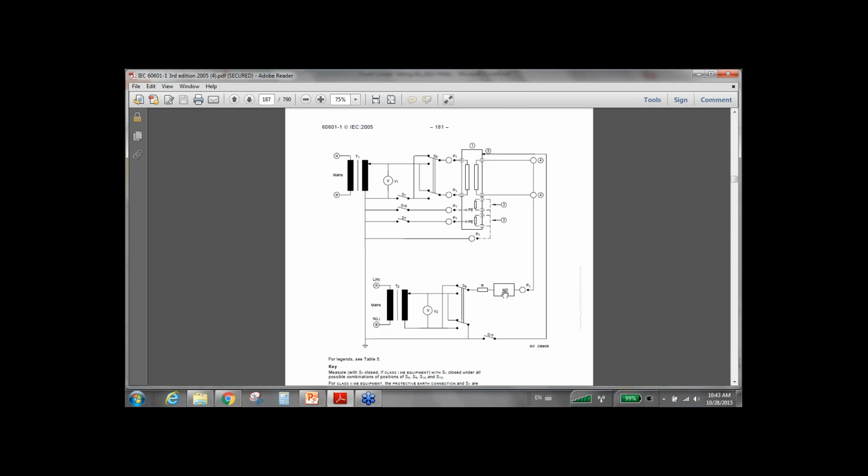and your measuring device is still between the patient lead, but now you're going to be applying a line voltage coming from a secondary transformer T2, which goes through a current limiting resistor, an optional resistor to protect the operator. And there's also a reverse polarity condition. So this is applying line voltage on one end of your measuring device,